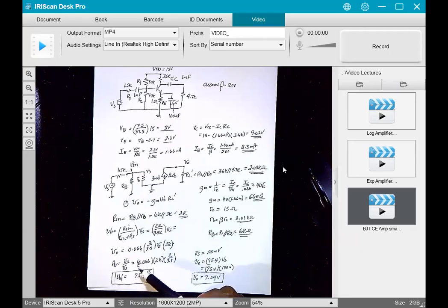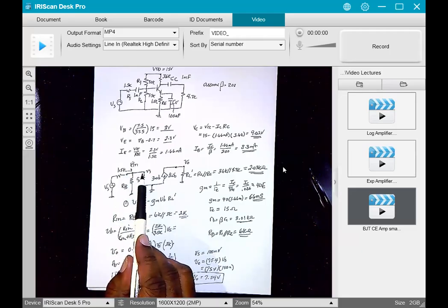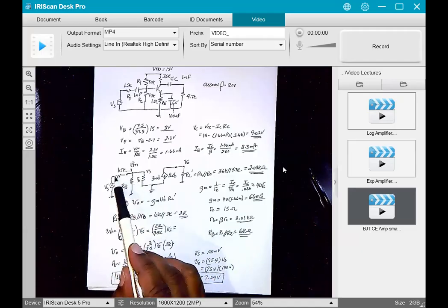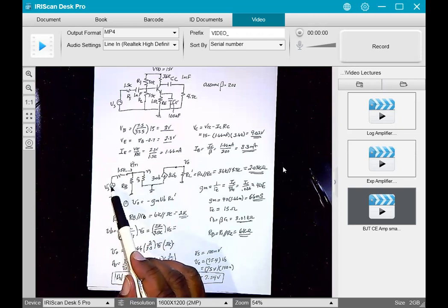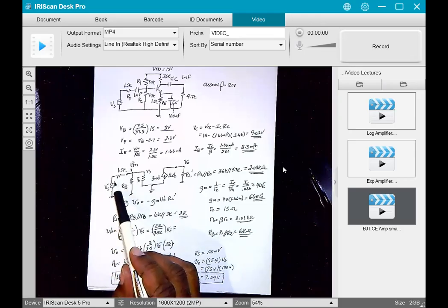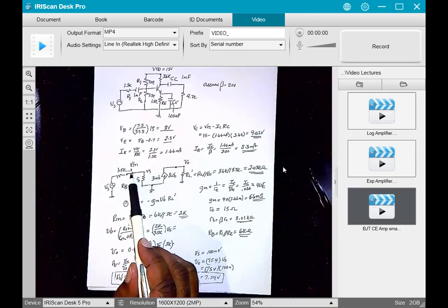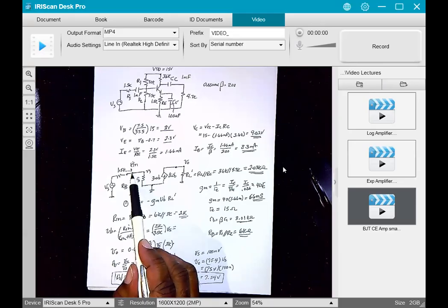Now I can make it easy for you and say that RS is 0. If I do that, what's VB? It's gonna be 0, right? Nope. If I made RS 0, VB is the same as what then? Yes, VS. Ain't no voltage division. This voltage gets applied directly to this node if this resistor's not here. So then VB will be the same as VS.